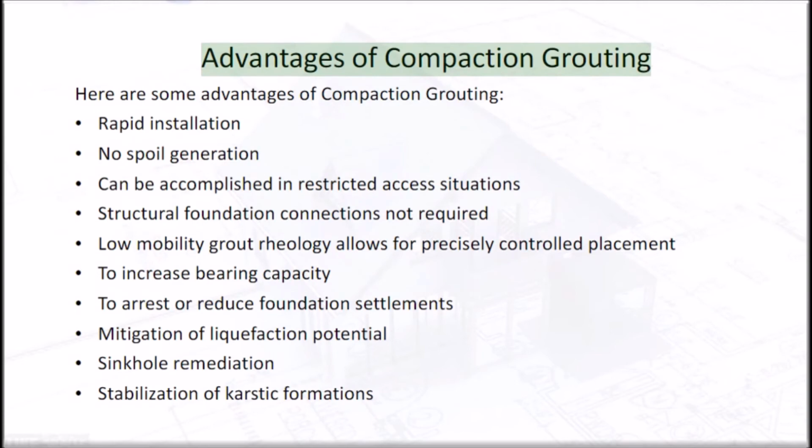Advantages of compaction grouting. Here are some advantages of compaction grouting. Rapid installation. No spoil generation. Can be accomplished in restricted access situations. Structural foundation connections not required.